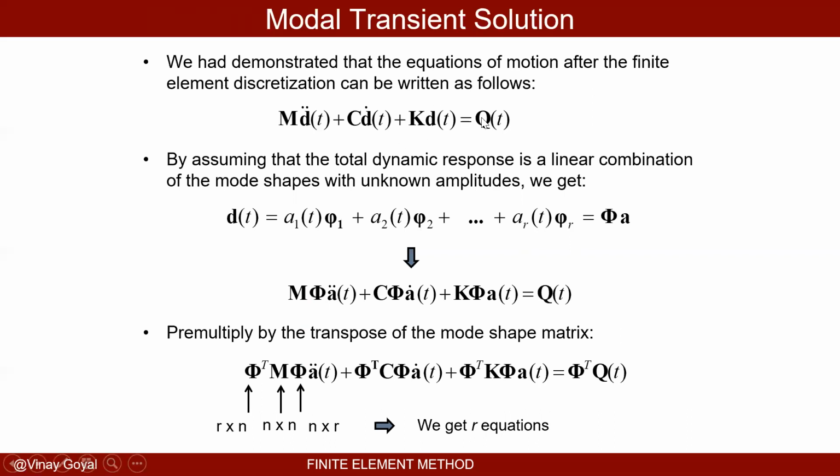Okay, so if I have millions of degrees of freedom, then M bold becomes millions times millions. So these are square matrices basically, and this could be computationally expensive to integrate over time. And depending upon the numerical scheme, you may have to invert the matrix even. So that is computationally expensive, and you have to keep track of that. It's not easy. It requires some amount of work.